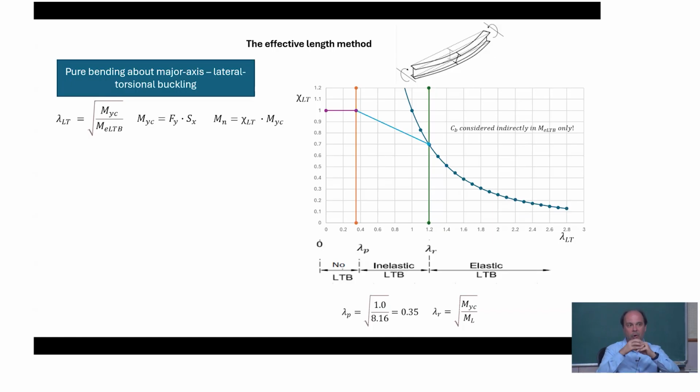So all the built-in impacts of the different stress distributions are in the value. An additional, a bit artificial multiplication is not recommended in the case of slender webs, because this additional positive impact in the intermediate slenderness section cannot be reached due to the difficult-to-take-into-account but existing deformations due to web shear.